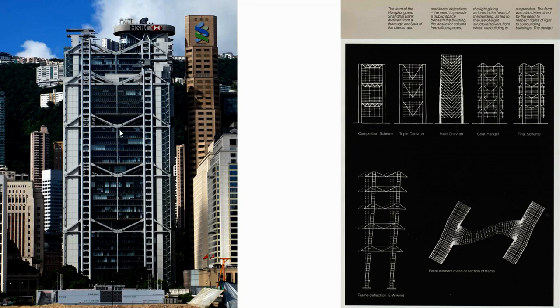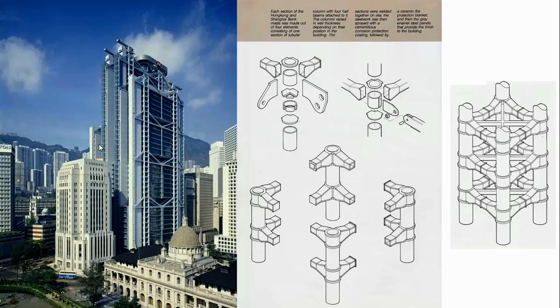All of these floors, so there's 1, 2, 3, 4, 5, 6 floors, are suspended from the coat hanger at that point there. That's what's making that very thin and very delicate floor. Okay. And there's some nice detailing that solves the problems of the multitudinous connections in this building.